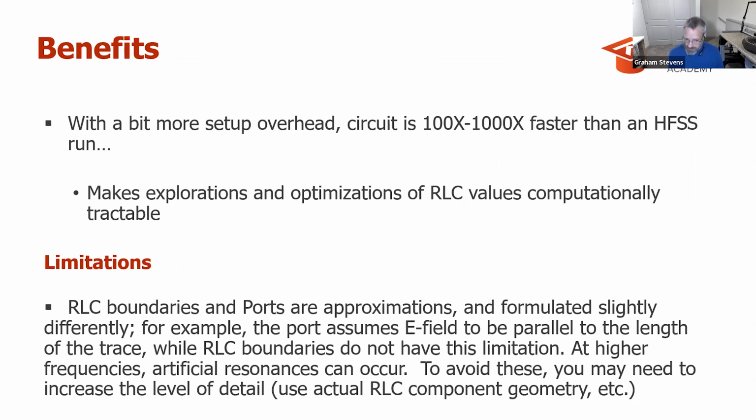And at higher frequencies, sometimes artificial resonances can occur. And so the equivalence of the RLC boundary and the port may not be exact at higher frequencies because of these artificial resonances. And so to avoid that, you may need to increase the level of detail in your analysis. Use the actual RLC component geometry, make sure the traces are equivalent as opposed to sheets, etc. But within this restriction, it's still much, much faster analysis.